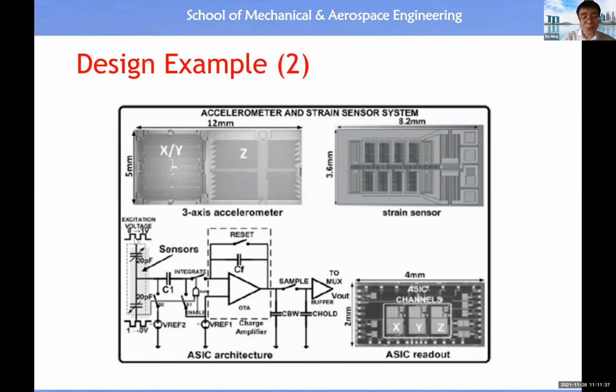And if you apply the background knowledge from a Fourier transform, it tells you any signal is a sum of pure sine functions. So actually, what does this mean? Instead of supplying a single sine function of a voltage, this is equivalent to saying we supply many sine functions of a voltage. You should not say there's no sine function in the input. Actually, it's not. You have many sine functions at the input, because this waveform is equivalent to a combination of many sine functions as an input.